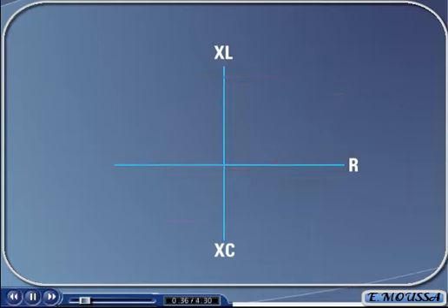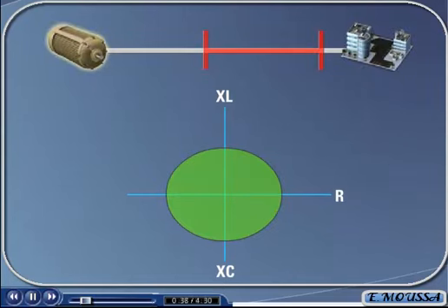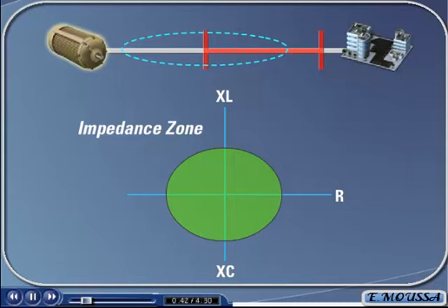Let's take a look at each of these operating characteristics for distance relaying operating zones. First, we will discuss the zone of protection known as an impedance zone. Any impedance that falls within the radius of the circle indicates a fault that needs to be cleared. The reach indicates in ohms how far on down the power system the zone of protection extends. This type of zone is inherently non-directional and will detect faults that occur in the reverse direction away from the point of measurement. This type of zone is normally used for generator backup protection.